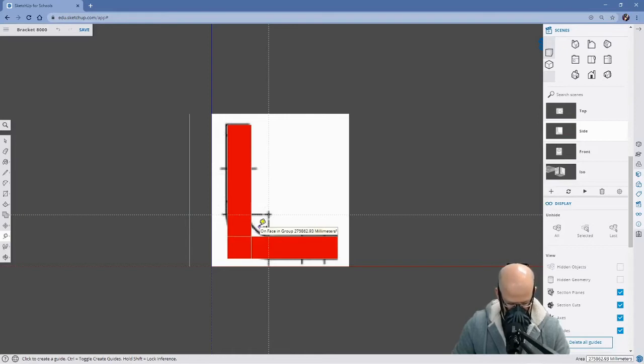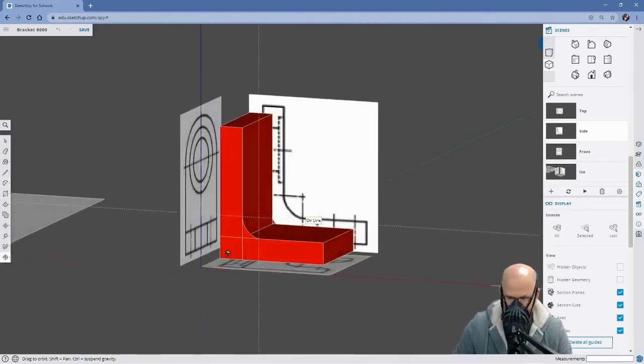movement. I will pull up A for arc tool, hotkey A. There's an intersection point. And I will come down to the other intersection point. I will click. All right. Let's see. Paying attention to my inference labels. Tangent to edge. There we go. That looks good.